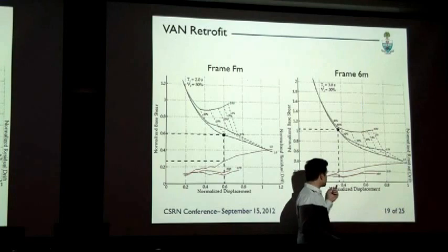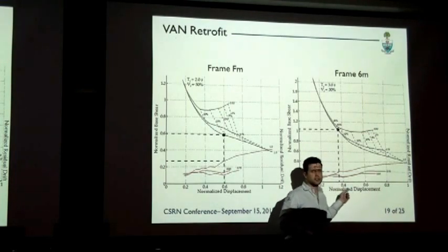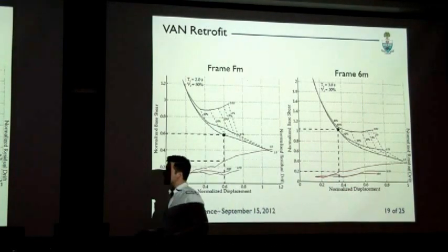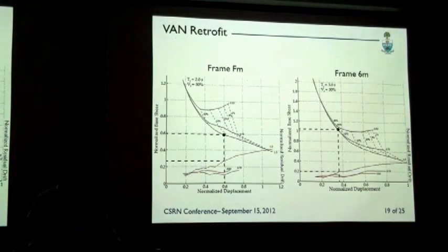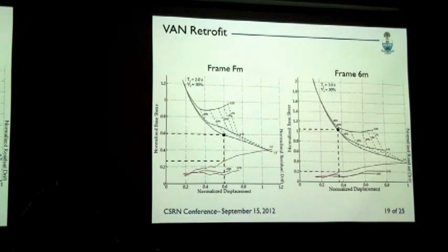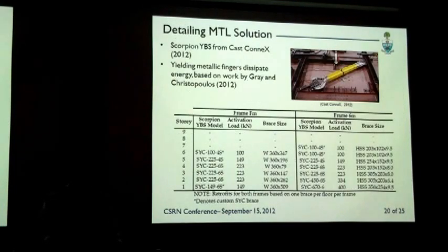We were really constrained by our performance target to reduce the displacement by quite a bit, and this required very high levels of damping, which will result in a very high increase in base shear, which will require very large damper forces, which we might run into problems in our columns. But let's go with this, run our nonlinear time history analyses, and see how it works.